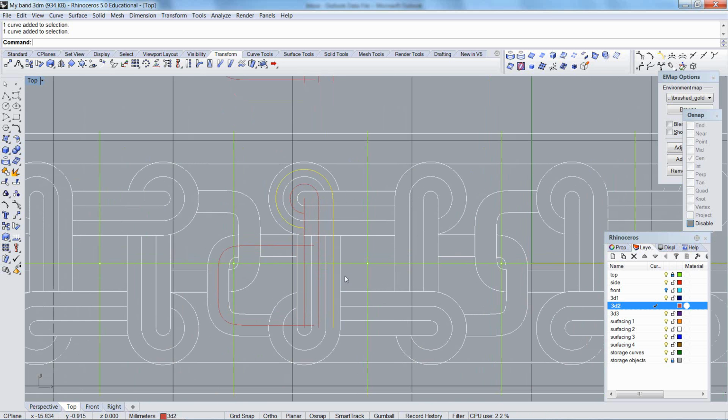Now I'm going to pipe. My wires are 1.2 millimeters thick, but because I've stacked them side by side, I need to overlap them more than that. I can't just do 1.2. I'm going to make mine 1.3 so I get an overlap on both sides. Okay?